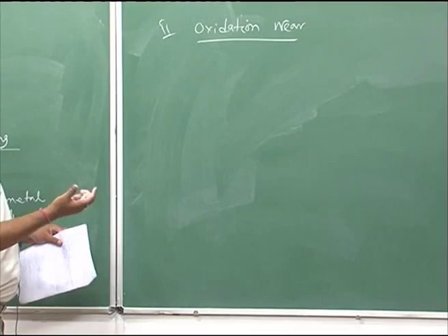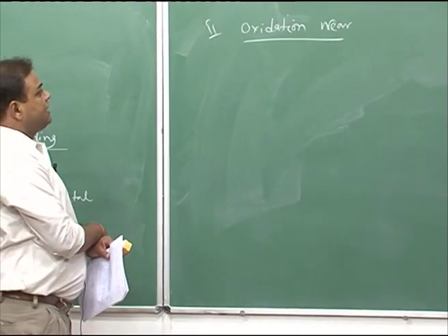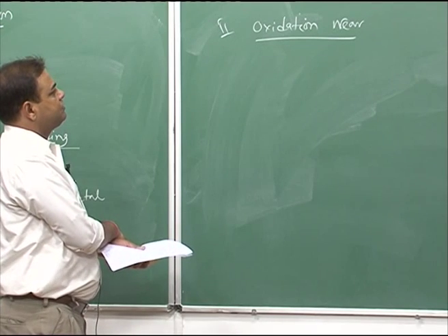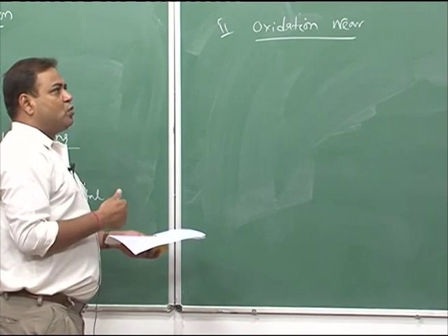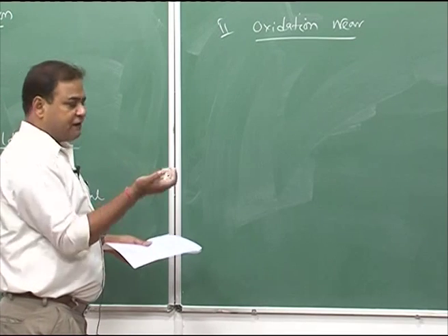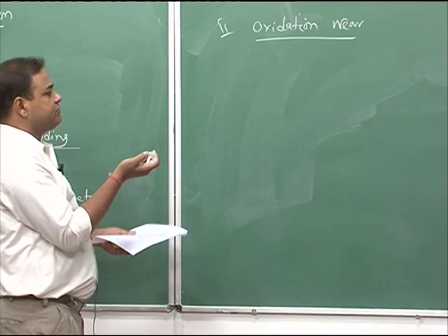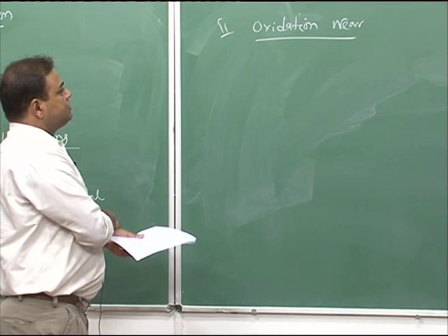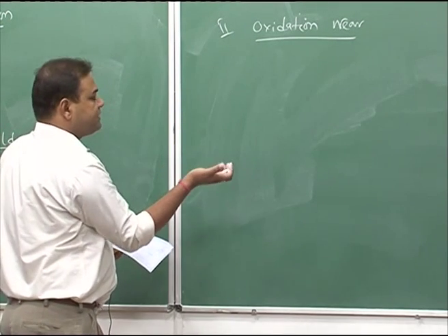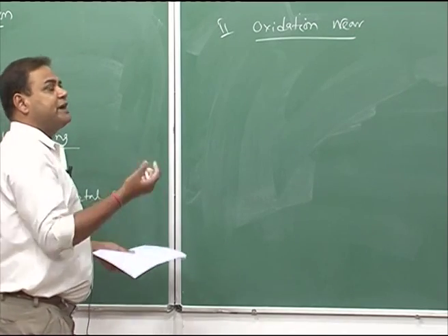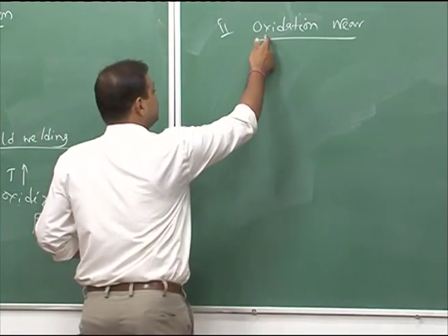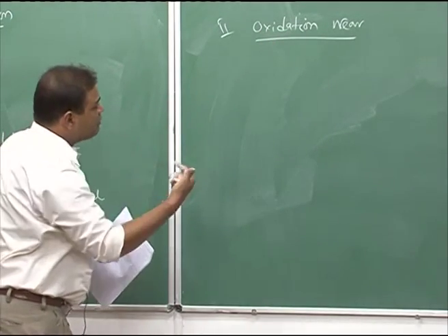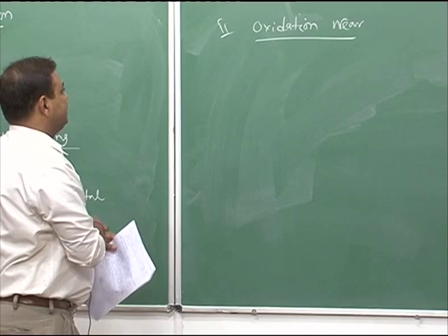First the metal surface would get oxidized, and due to this friction action and the application of pressure, the oxide layer would be chipped off and the fresh metal surface would be exposed to the environment, and that exposed fresh metal surface would get oxidized again. So, the oxidation is occurring first, and the wear effect is actually removing the oxide layer.